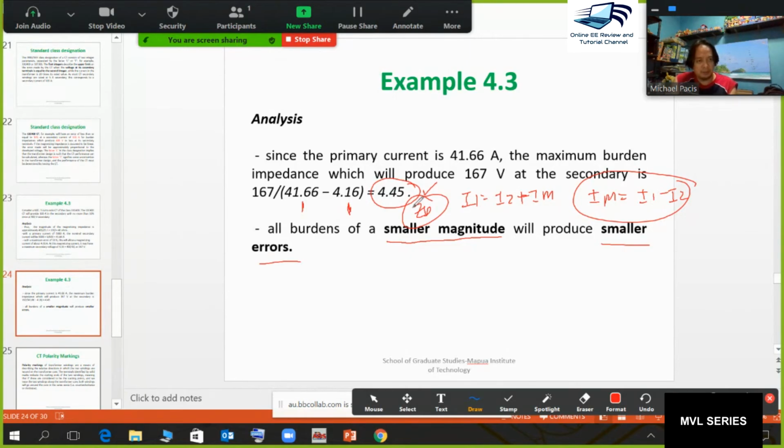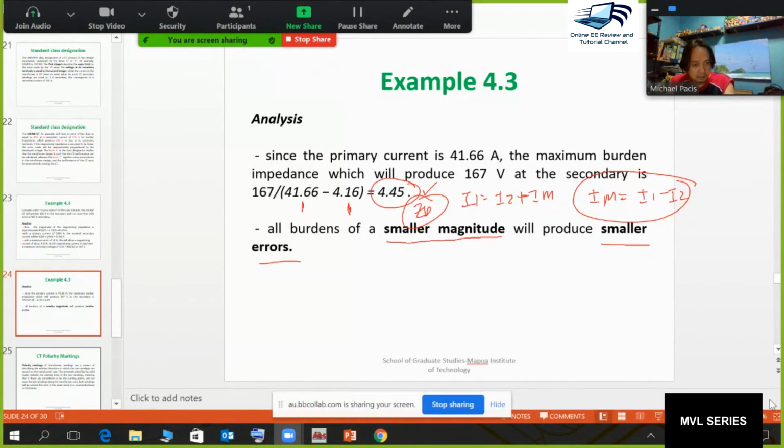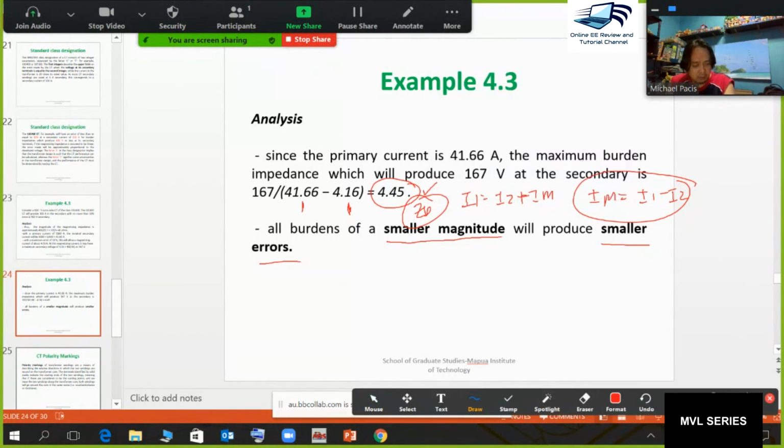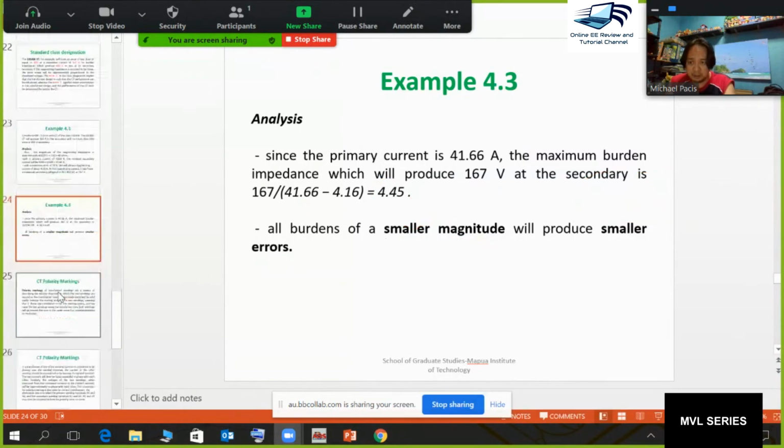If you want to have a lower value of the burden impedance, perhaps you can lower the transformation ratio in a certain way that will yield a lower resistive value. As we mentioned in problem 4.1, a lower resistive value will mean a lower correction factor, and a better effective turns ratio. From there, you'll already learn some things on CT design, or current transformer design.